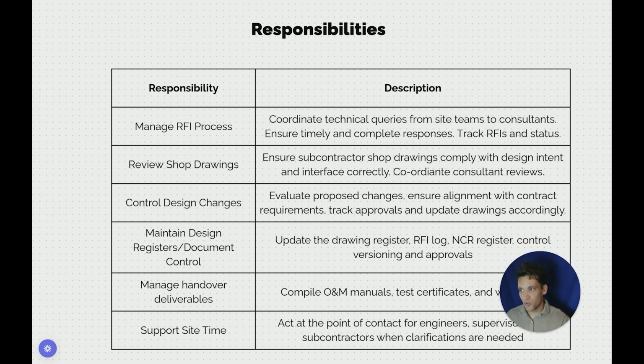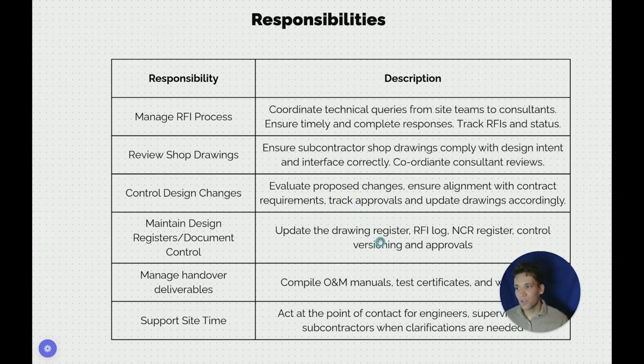They're also reviewing shop drawings, or at least sending them to the consultants to review. They're ensuring that subcontractor shop drawings comply with the design intent and interface correctly, and coordinating any consultant reviews. They're the ones controlling design changes, so they're evaluating the proposed changes to ensure alignment with the contract requirements, track approvals, and updating the drawings accordingly.